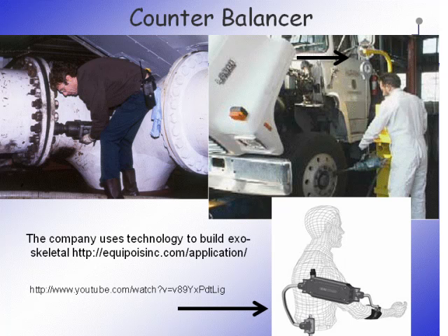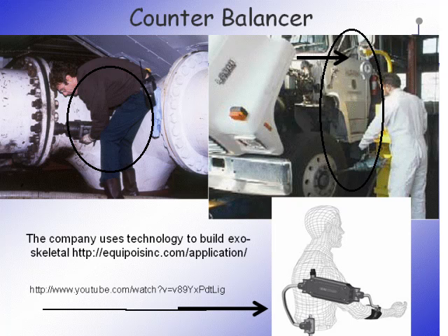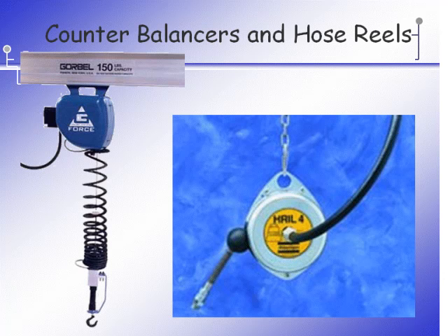So your counterbalances, this is an example of where this poor gentleman could really use a counterbalance tool. This impact wrench is well over 25 pounds. And the problem with the impact wrenches is when you reach that set point, that's when that tool starts to kick in your hand, and you create that impulse or that impact on the worker's hand. And here we're just counterbalancing the tool with an engine hoist or a cherry picker. And again, this is a website that's up there for you to take a look at some really great technology. We were putting this technology in place when I was working with the United States Navy.